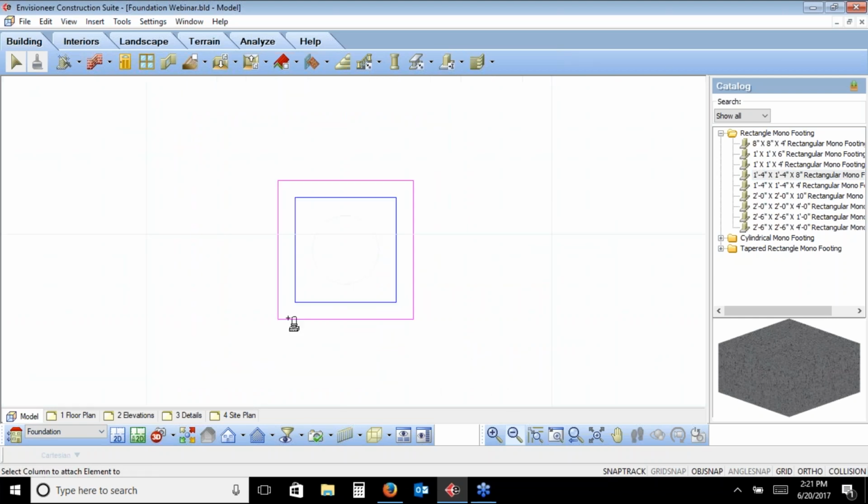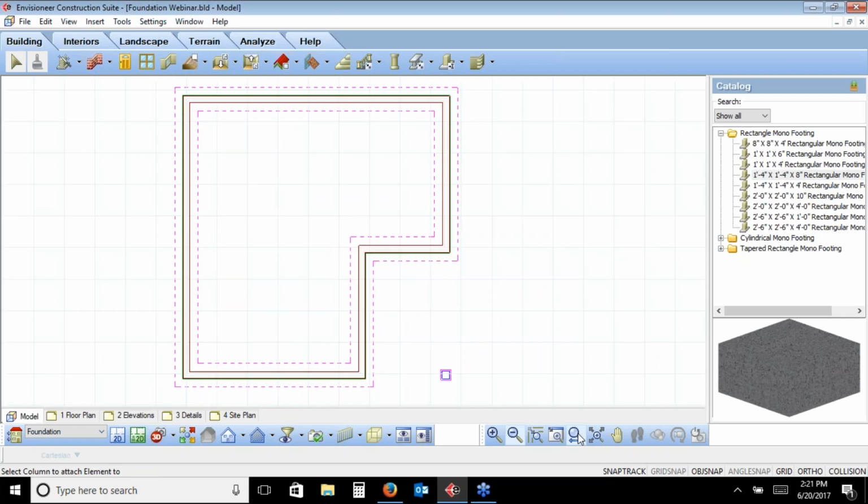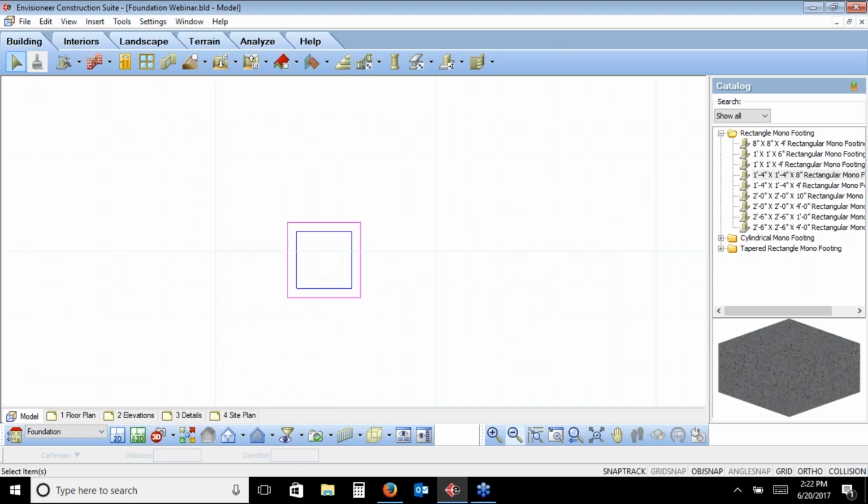And I'll just zoom in there so you can see the footing going all the way around it. So it's automatically put a footing underneath it. For those of you that are using pier footing situations where you're going to have your pad footing and then maybe a concrete or a brick pier system being built, you could put in one exactly like I just did here. Put in your concrete column, put in your pad underneath it, and then depending on how that pier system is being supported, what we're going to do next is we could even array these. So I could select the column.